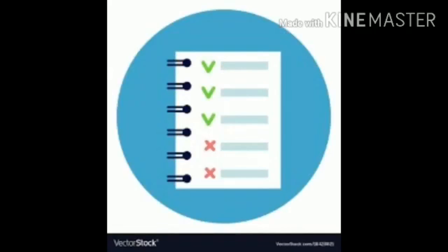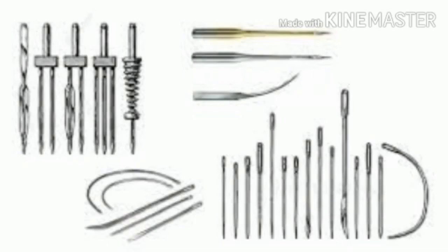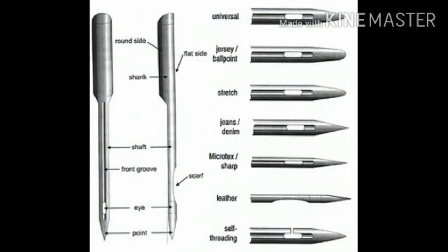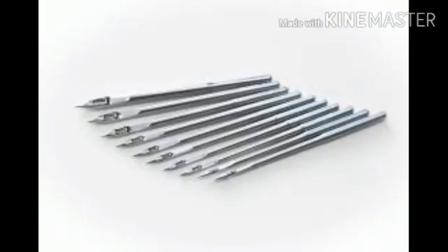As Lukman has just discussed cleaning procedures, now I will be discussing some checkpoints before working on a stitching machine. One of the most important and basic checkpoints every operator has to follow every day is to check whether the type of needle being issued is correct or not. Look for the correct size. Also, a worker must check whether the point of the needle is suitable for the fabric. The thickness of the needle should also be decided according to the type of fabric being used.